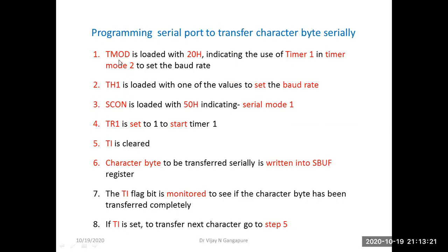So first step is TMOD. TMOD is loaded with 20H. TMOD is the timer mode selection register.